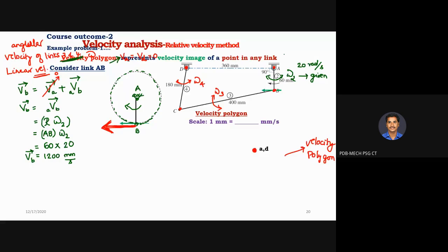Yes, towards the left side. You would have drawn the configuration diagram for AB. You need to draw a line perpendicular to it from point A in the velocity polygon. So check whether it is correct or not. Is it perpendicular to AB in the configuration diagram? Yes, sir. And it is acting towards the left because your crank is rotating in the clockwise direction. So as I told, in this case it should act along the left-hand direction. Is it correct? Yes, sir.